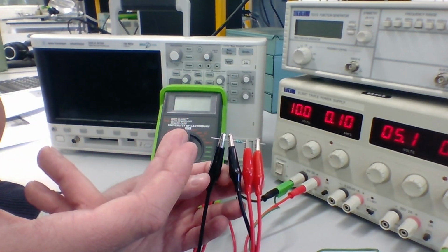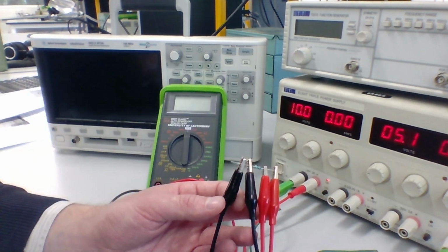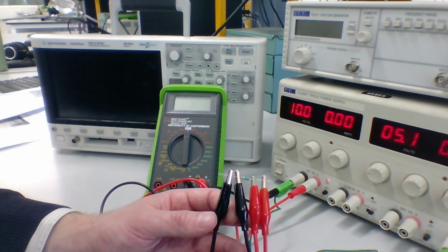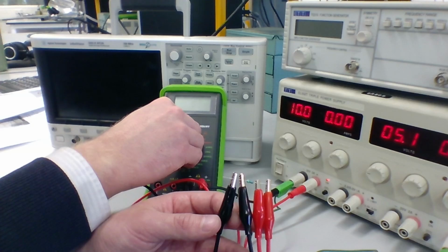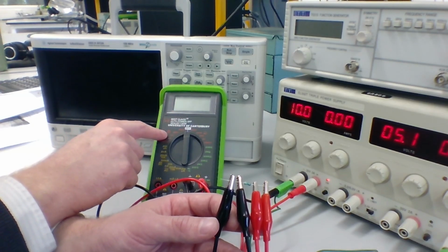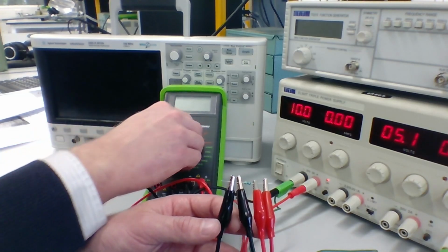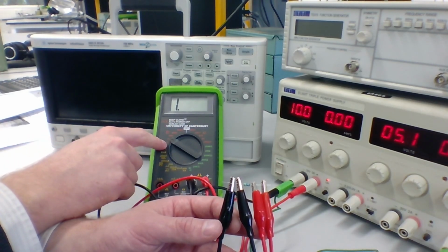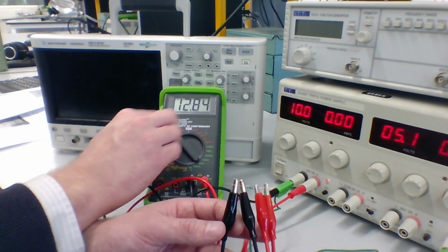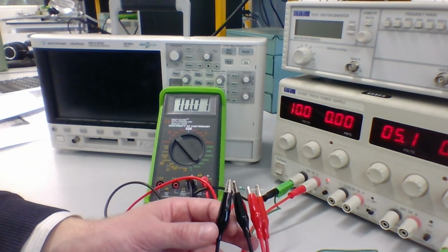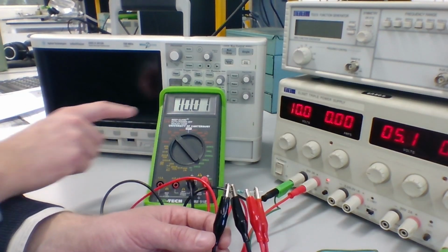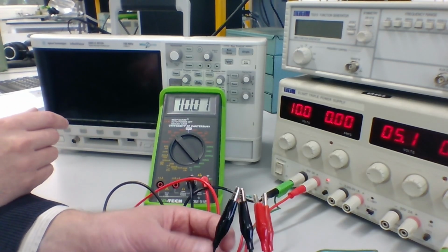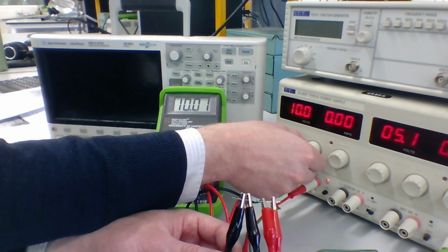So now I have the power supply connected across the resistor and the multimeter measuring across the resistor as well. I can then turn the power supply on, and I can measure the voltage across this resistor, which is the first thing you'll need to measure here. So I turn the dial on the multimeter to the DC voltage measurement side, again to the appropriate range I expect. So if I turn this to the 2 volt range, it's just a little bit too small. If I turn it to the 20 volt range, I'll get a decent measurement. Here I can see I'm getting almost exactly 10 volts across the resistor. In fact, I'm getting 10.01 volts, which is close enough. I could adjust that using the fine voltage dial if I want to.